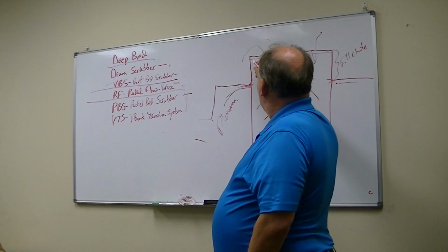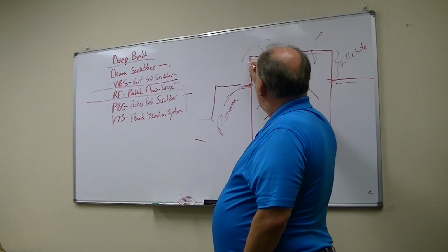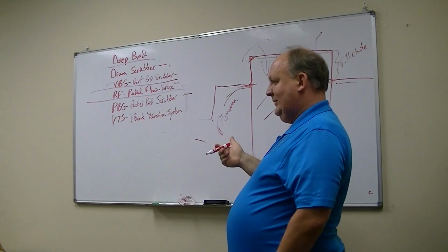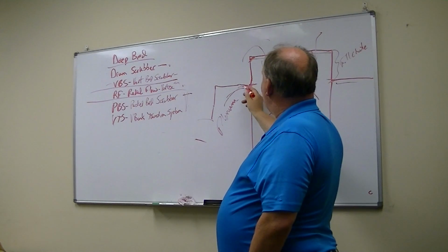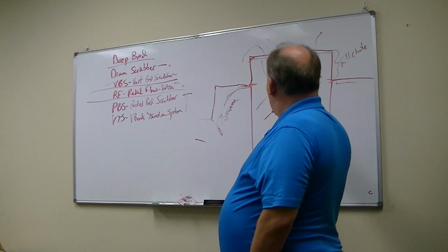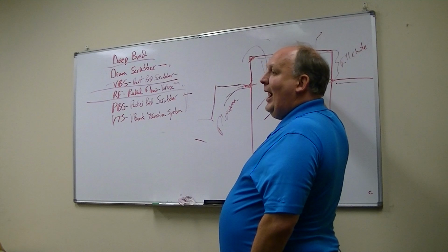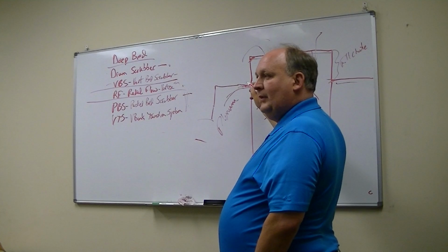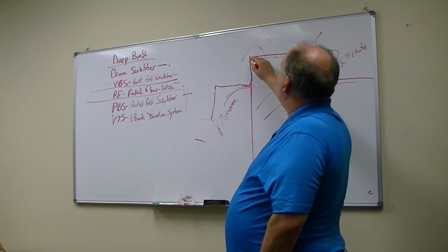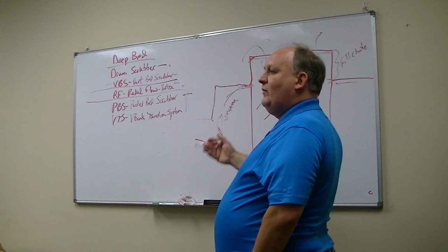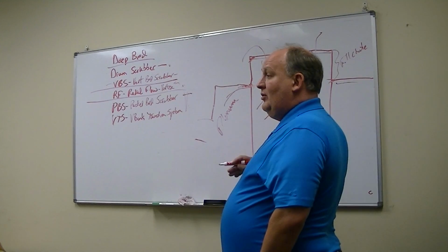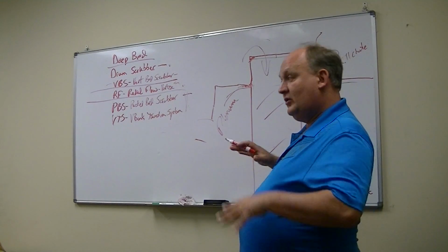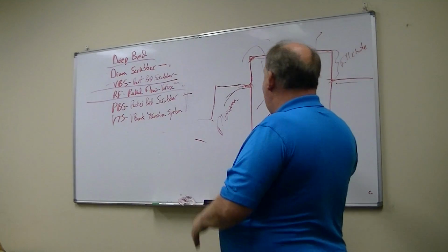So we get the contractor who's installing this system, and we tell them, make sure to fill this thing to this level here. All the time, they want to fill it to this level here. One, because it's less work, and two, because they think that because the screen's here, they only need to fill here. And we have to tell them all the time, no, fill it all the way to the top of the Fill-Chute. Even if you tell them, fill it to the top, they'll think this is the top. Yeah, I know, it's the most frustrating thing. Fill it to the top of the Fill-Chute, almost so it's about to overflow. I've done it, I've been on top of it, and I've put my foot on it and stamped it down to try to make it settle a bit and really get it packed in here.